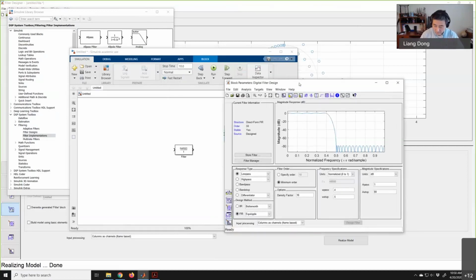Okay, that concludes what we need to discuss for today. I've shown you how to use a computational tool, Matlab, to design a filter. It can really ease our work. Starting from the ideal case, what we want, we translate that into specifications, and use those specifications to design the nonideal limits. Using that, we find h[n], the digital filter. You can export that into your program, or import it into Simulink and then link it to the signal that you're dealing with.